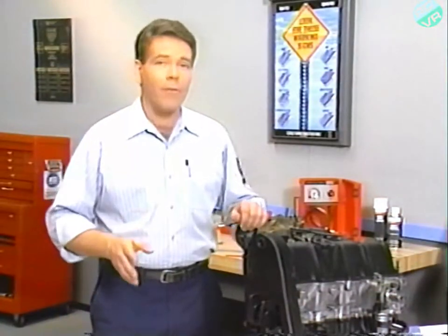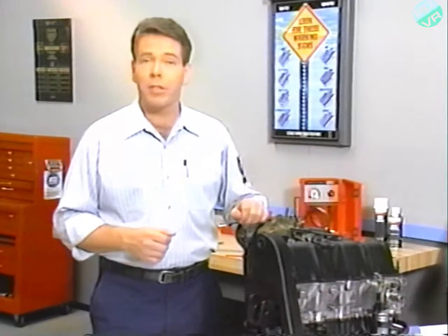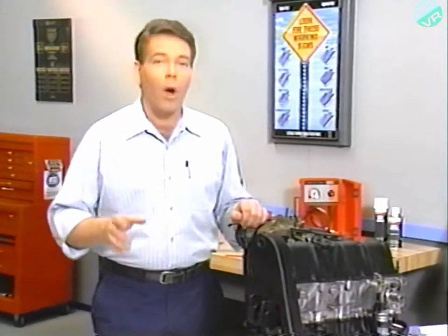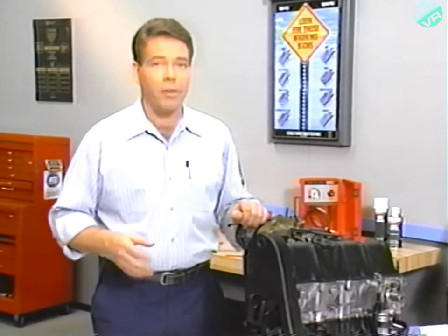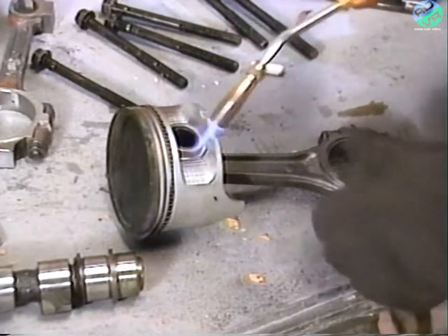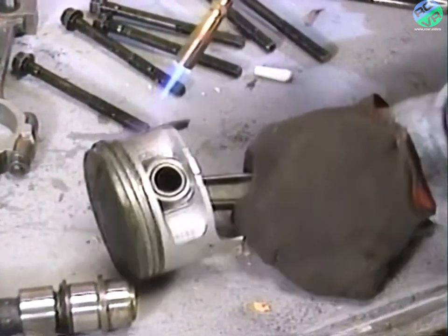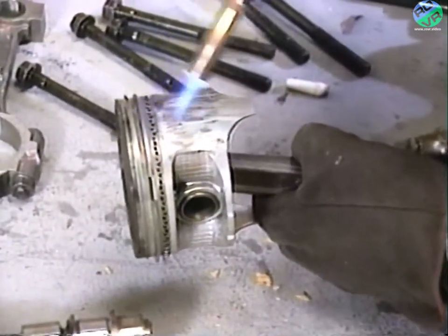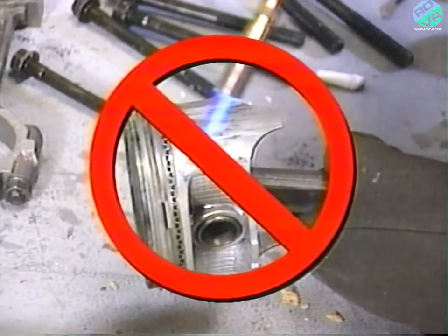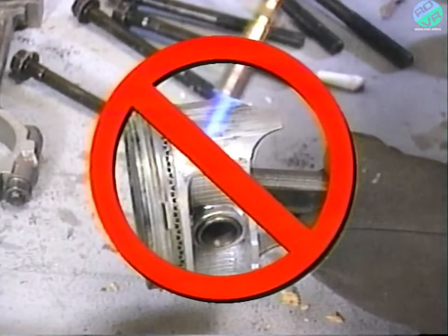If you don't have the correct tools for piston removal and installation, send the piston out to a machine shop. While there, have them check the connecting rods for bend and twist. Under no circumstances should you ever attempt to remove a piston by heating the piston with a torch and then beating the piston pin out with a mallet. This will heat treat the piston, damaging both it and the piston rings.